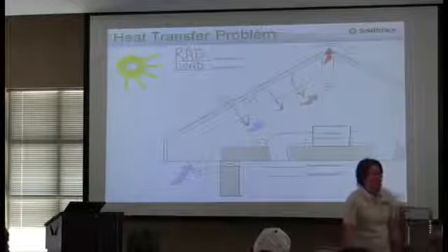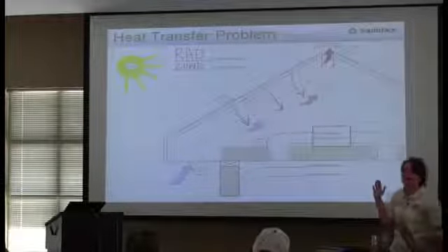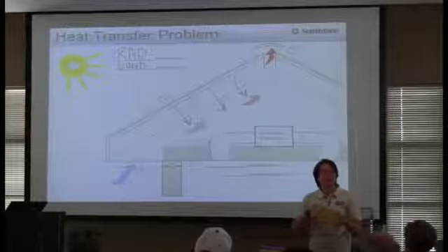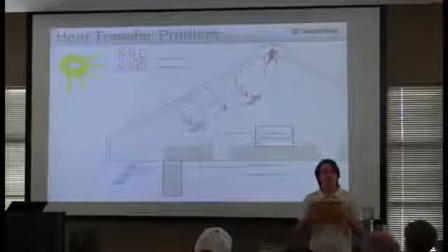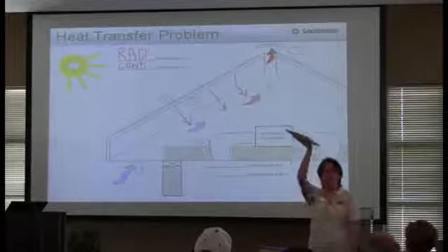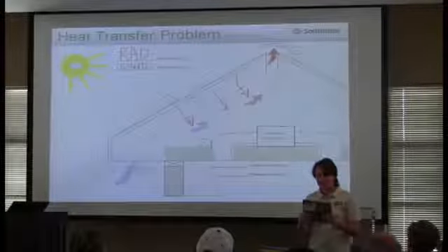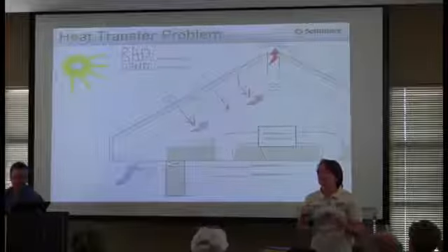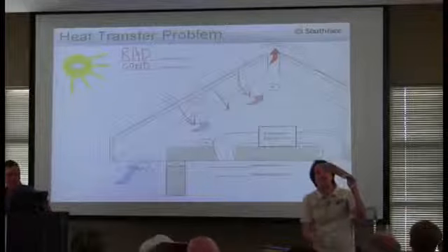Whatever. All right, from 3 to 4, again, it's radiating, which is why they create materials like this, where you have the decking that you would have used just normally, right? You would have just put this up there just like that, no problem. They actually create a silver film, or aluminum film, that goes over it that prevents that radiation from coming down, or slows it down.